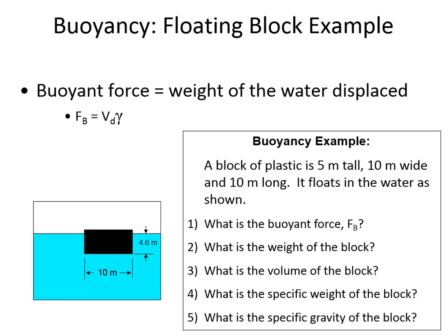In the lab today, we're dealing with buoyancy. You're going to be doing 2 different things. You're going to be measuring how deeply submerged a plastic box is. It's actually like a little boat. You're going to find out how deeply submerged it is with a known weight. And then you're going to put an unknown weight into this little boat and see how deeply it's sitting. It's kind of like a barge. You're going to take a look at how deeply it's sitting in the water in order to estimate what the weight of the unknown object is.